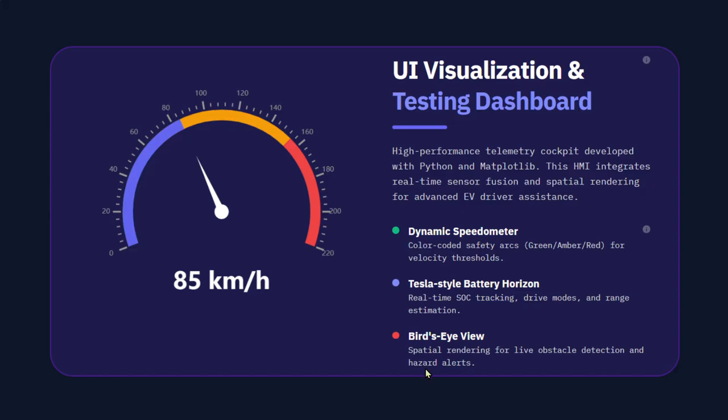Bird's eye view. Finally, in the bottom right sector of the interface, I handle the separate radar readings, converting the millisecond echolocation delay for our front and left and right ultrasonic sensors into a real-time top-down map view, with an automatic flash warning if a vehicle creeps into our blind spot on the highway.